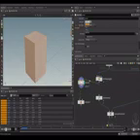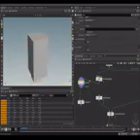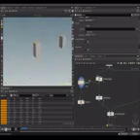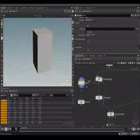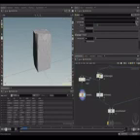Go to the set this to edges. I'm gonna call this group edges. And this will work because I'm taking exactly edges. So let's go back to the remesh node and set the hard edges to edges.